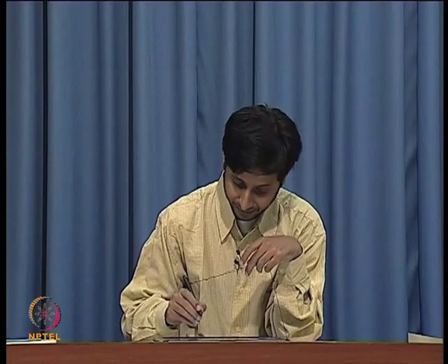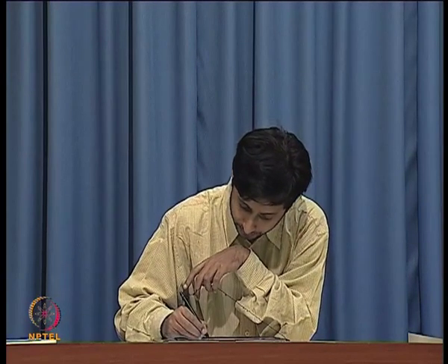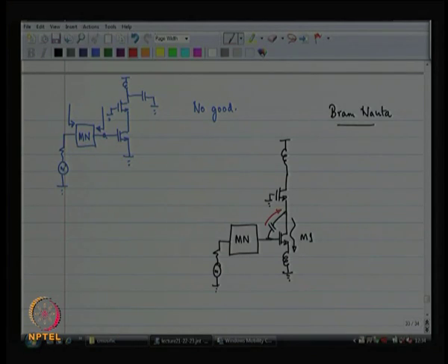Part of this noise current is going to come from this capacitor. Part of it is of course going to be sourced through the second MOSFET, because it is a low impedance node. But if I artificially place a second capacitor over there, I can have some noise coming out in the other direction.